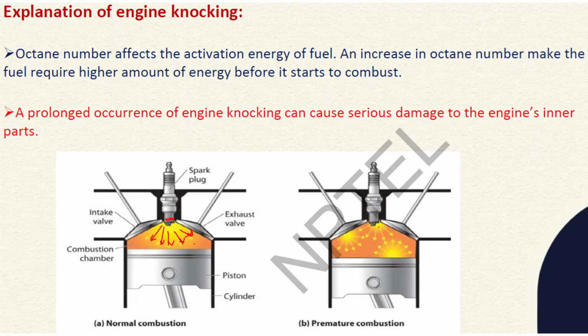But after some time, when rapid combustion of the remaining amount of gasoline starts, localized burning of the gasoline inside the cylinder takes place, due to which the knocking takes place and the inner lining of the engine gets damaged, which further decreases the lifetime of the engine.